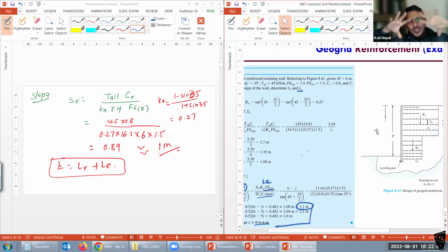It's the same process for all 3 types of reinforcement wall design. The only thing is metal strips: you need to calculate horizontal and vertical spacing, not only vertical, for geotextile and geogrids. We need to calculate both designs. I think some of you chose the soil stabilization project. I thought you would go a little bit in detail in the design and show some example design of the wall, but you mostly focused on just the soil improvement type things, not the retaining walls design.